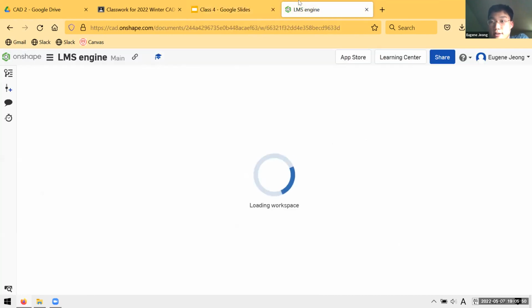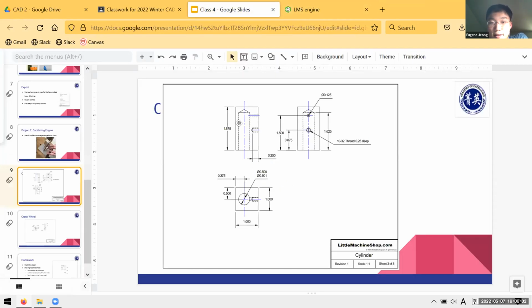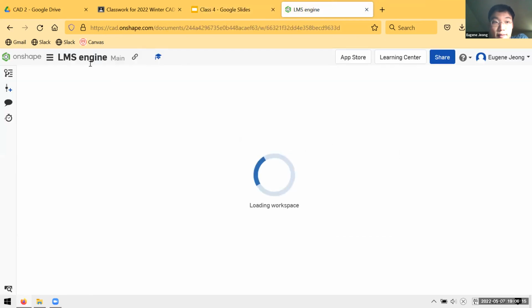What about to go to 3D? Which tools would you use? These circles. Yeah, you do need circles. As you probably noticed, there's a circle here, and then it extends with hidden lines into the body. So that indicates that there is some kind of blind hole or bore that goes into the part.